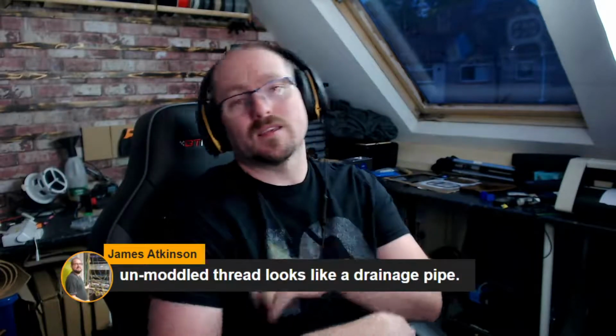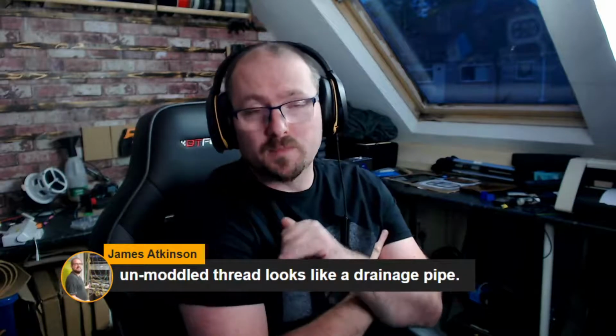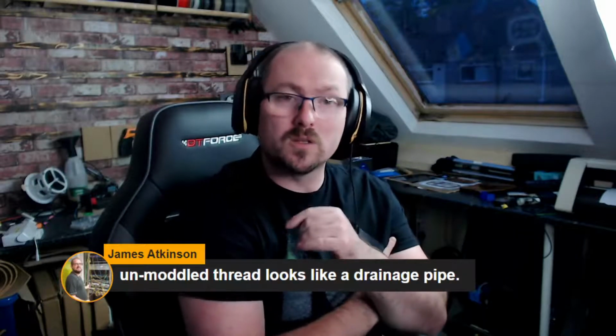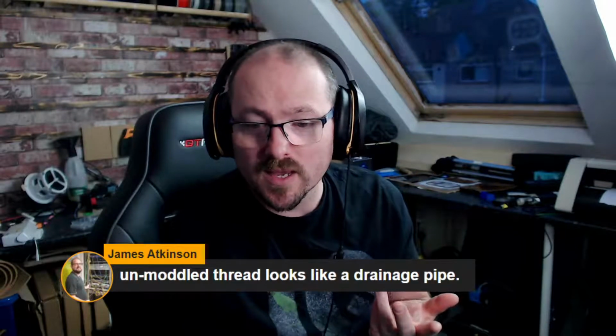The second thing that you need to take into consideration is the machines being used and your ability to use those machines. We're looking at 3D printers and how accurate they are. When you 3D print a 25 by 25 by 25 millimeter cube and you put a set of digital calipers on it, you get to understand what discrepancies there are in the manufacturing system.